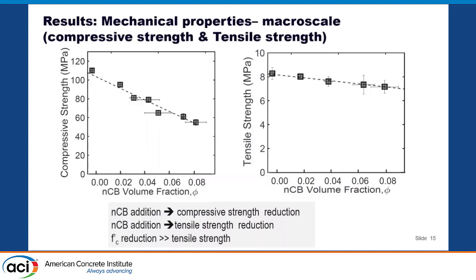Yes, actually, even according to my paper, and under my patent on ultra-high performance glass concrete, we achieved a strength of 230. Because I believe the carbon black is a very hydrophobic material and has a tendency to agglomerate. We started with a low water-binder ratio of 0.25, but we couldn't make concrete at 0.25, 0.2 and 0.17. So to trade off between compressive strength, mechanical performance, and electrical properties, we went with the highest water-binder ratio in ultra-high performance concrete, which is 0.25.